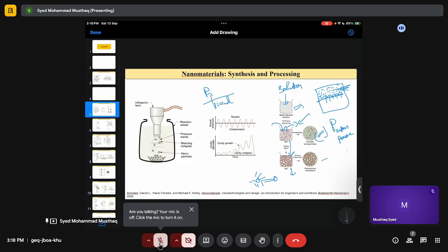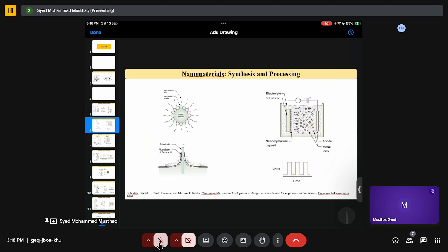Yeah, we formed a nanoporous membrane, right? That's all. So for 3-dimensional structures, we use sol-gel. Now if you want to make 1D or 2D nanomaterials, for that we use this Langmuir-Blodgett technique to form a 1D thin film, right, which is a self-assembly structure.